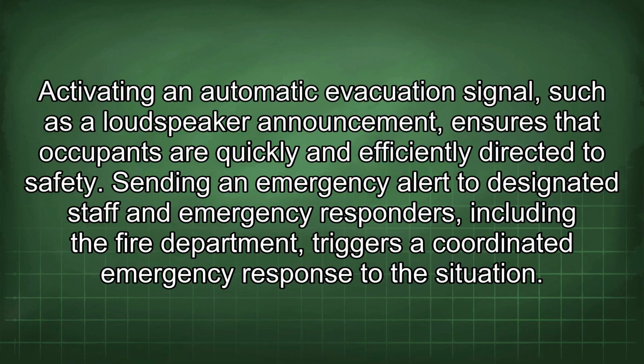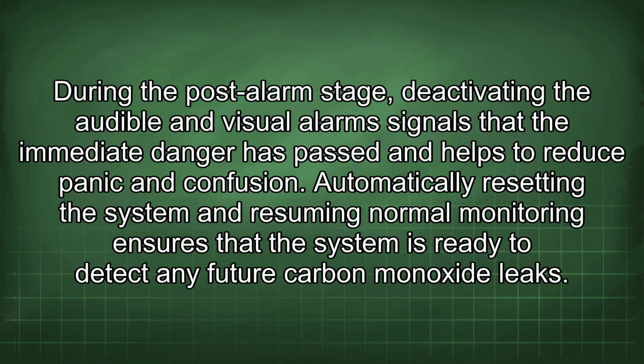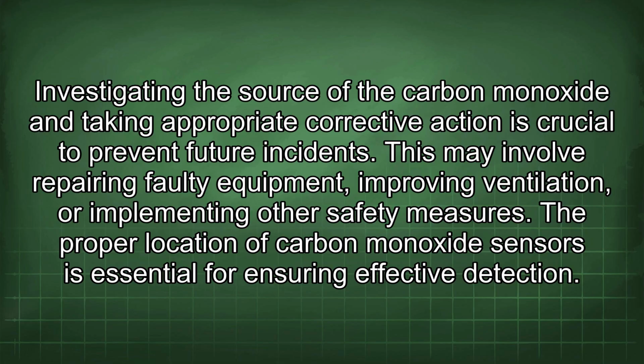During the post-alarm stage, deactivating the audible and visual alarm signals that the immediate danger has passed and helps to reduce panic and confusion. Automatically resetting the system and resuming normal monitoring ensures that the system is ready to detect any future carbon monoxide leaks. Investigating the source of the carbon monoxide and taking appropriate corrective action is crucial to prevent future incidents. This may involve repairing faulty equipment, improving ventilation, or implementing other safety measures.